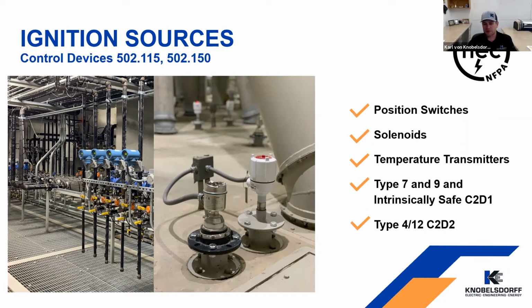You'll see in the picture the different types. This is on a bin deck. The picture on the right is a point level transmitter, which would be a NEMA type 7 enclosure, which is dust ignition proof, could be in a class 2 div 1 location. And on the left is a 24 volt instrument area level transmitter, which is an intrinsically safe device.